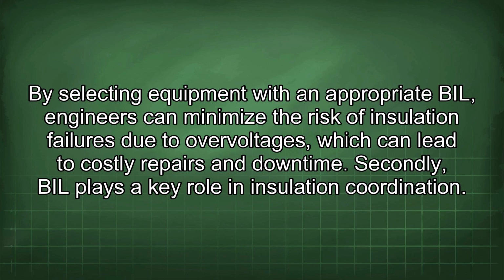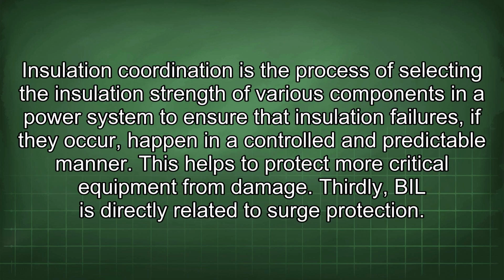Secondly, BIL plays a key role in insulation coordination. Insulation coordination is the process of selecting the insulation strength of various components in a power system to ensure that insulation failures, if they occur, happen in a controlled and predictable manner. This helps to protect more critical equipment from damage.